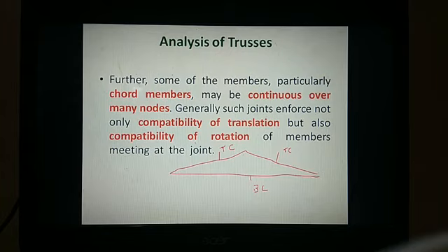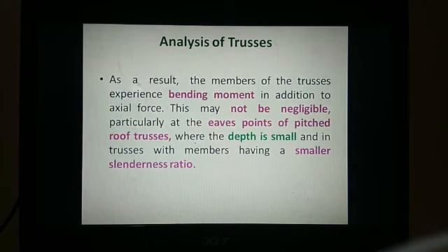Particularly in the main members of the roof trusses, as a result, the members experience bending moments also, in addition to axial force. This may not be negligible, particularly at the eave points of pitched roof trusses. What do you mean by pitched roof trusses?